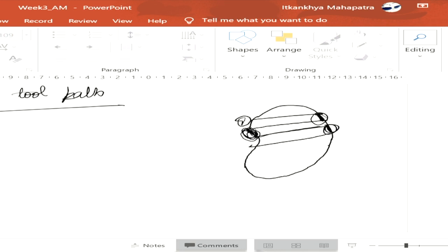So boundaries of the contour are approximated by linear edges. However, due to discretization errors, which occur on edges not parallel to the tool motion, the outline is sometimes poor. So this leads to poor surface quality of the printed part. But this has less build time and fewer transition motions.